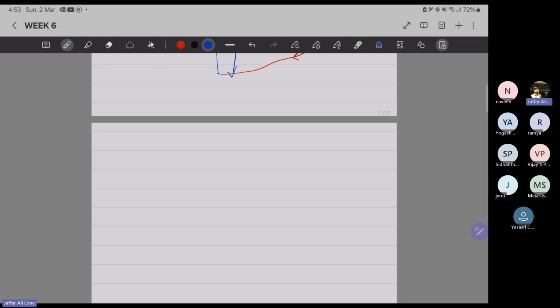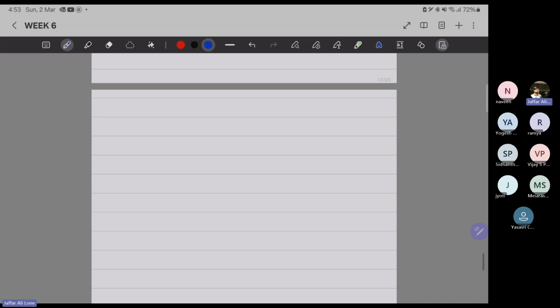So that's not easy to cover in a normal plot. So what we do, we make Bode plots. In Bode plots, we plot magnitude in decibels, right? And with respect to omega, which we are taking in the log axis, log scale, right? So whenever you are given a magnitude, in order for you to compute magnitude in decibels, you need to multiply that with 20 log, right?